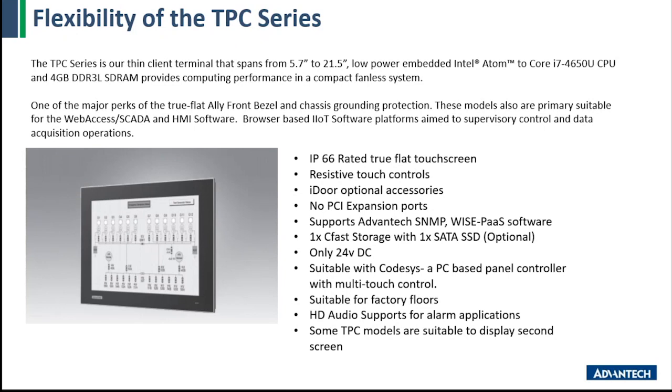And the real cool thing about these models is that, being such a thin client, you don't have to worry about high CPUs with these ones. The entire range of these TPCs will purely be Atom processors or Celeron processors, because Advantech know that when it comes to certain SCADA programs, you don't require a large CPU power. So there's no real point in us offering a customer an i5 model in a certain size when we can just provide a TPC model, and also make sure that the model itself is well designed for your requirements.